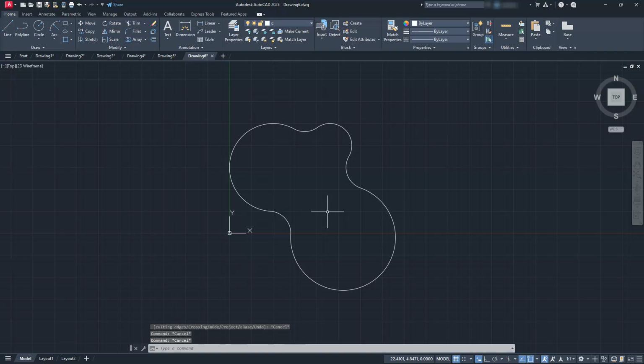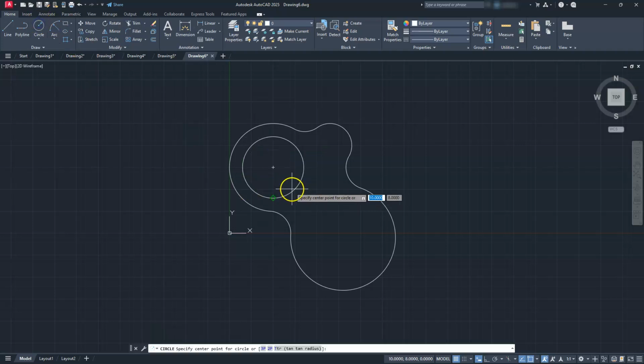All right. Now I'm ready to go ahead and put the circles on the inside of here. So I'm going to go to circle. I'm going to go find this center, click here. I have a circle that has a radius of 7. I'll go back to the circle center radius command. And then I have one that's set on the inside of this one that has a radius of 5.